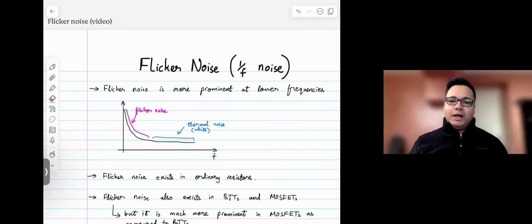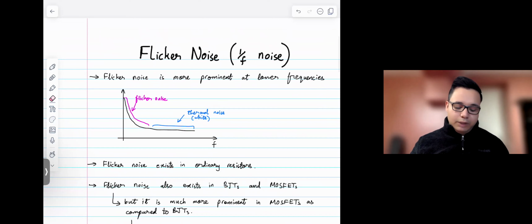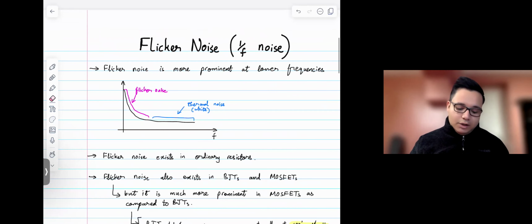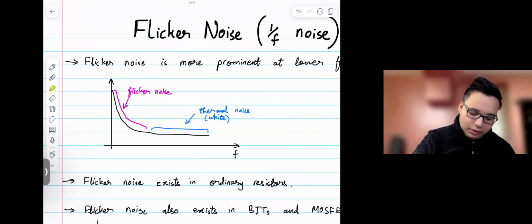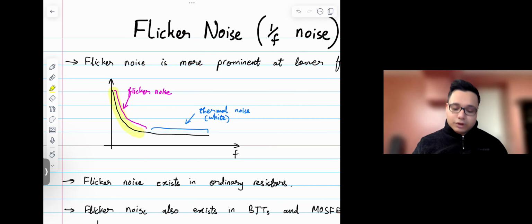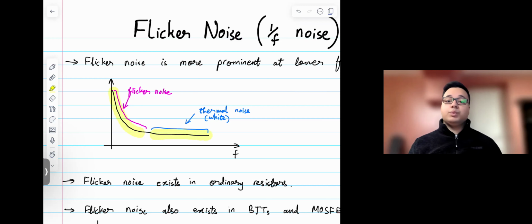Hey everyone, my name is Bhaskaram, and in this video we are going to talk about flicker noise, also called 1 by F noise. The first thing I want to talk about regarding flicker noise is that it's most prominent at lower frequencies. A typical noise profile might look something like this, where you have contributions from flicker noise at low frequencies, and then that contribution rolls off, and then you have contribution from thermal noise, which is white in nature and goes up to very high frequencies.